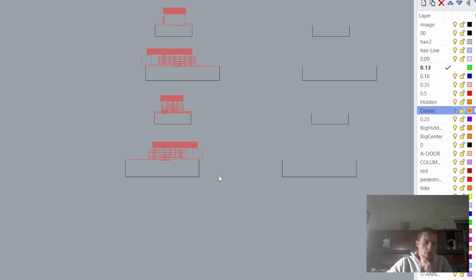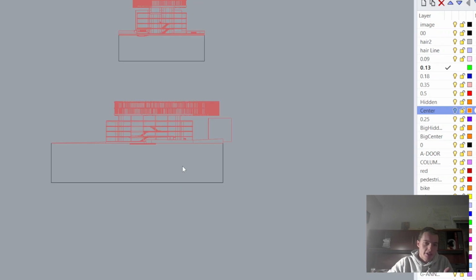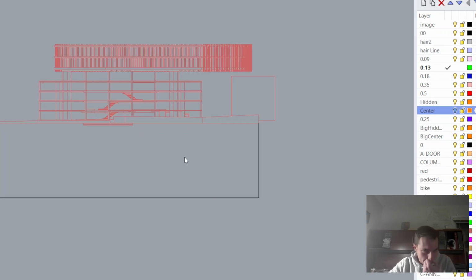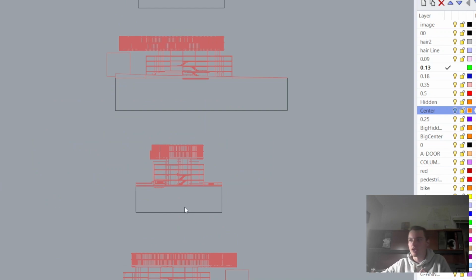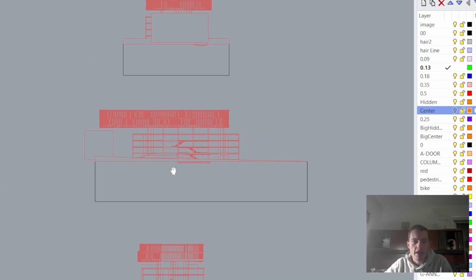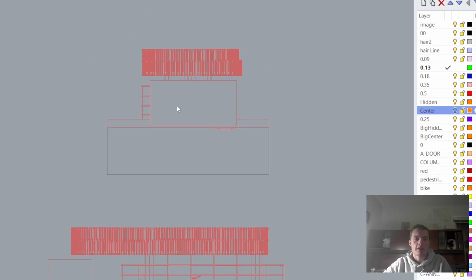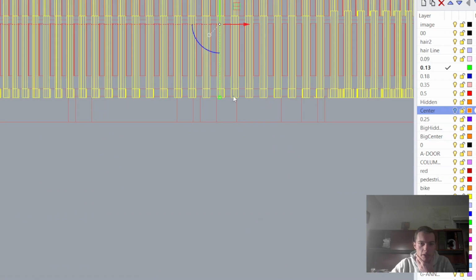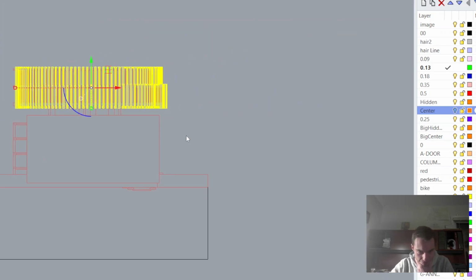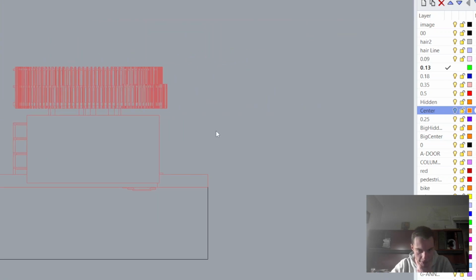Well, when you take your drawings from Rhino, at least in my experience, this Make 2D command turns out badly, and it shows a bunch of lines in the background, and who knows what's going on. So basically the skeleton of the drawings is what I have right now, and I haven't separated them into the proper layers yet, which I still gotta do.